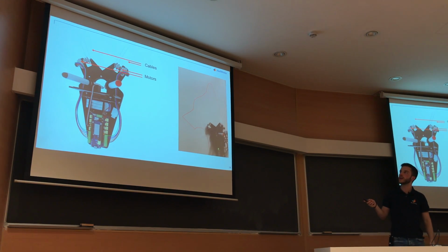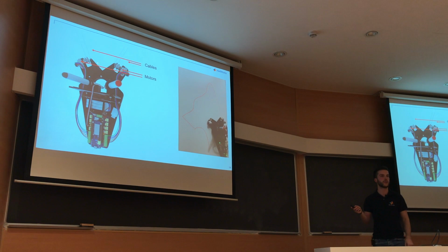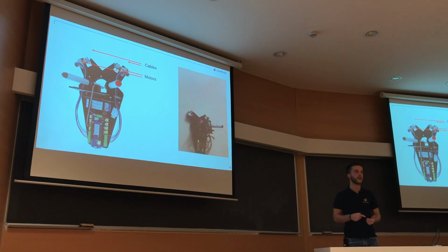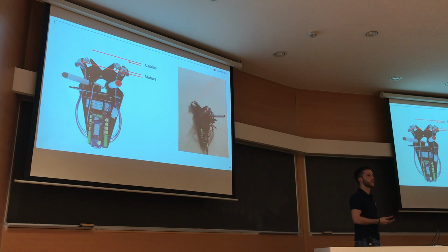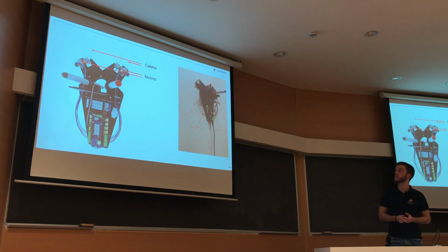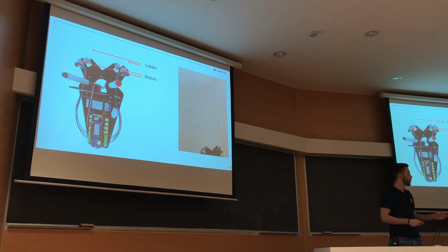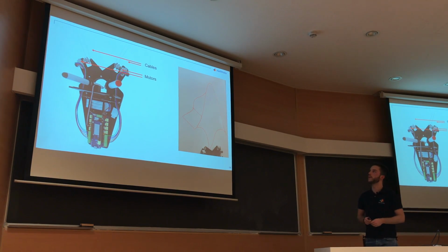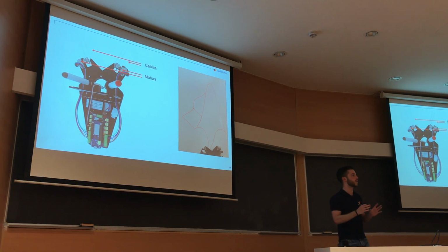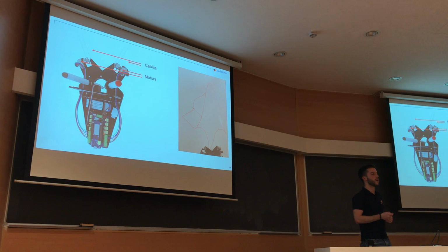These motors are DC motors with encoders, so we can know the position of each motor at each time instant. So we can actually compute, with the mathematical computation that Albert will show you in a moment, the position on the whiteboard, provided that we know the rotation of the encoder. Is it clear? These are the 2 actuators for the positioning of the robot on the whiteboard.